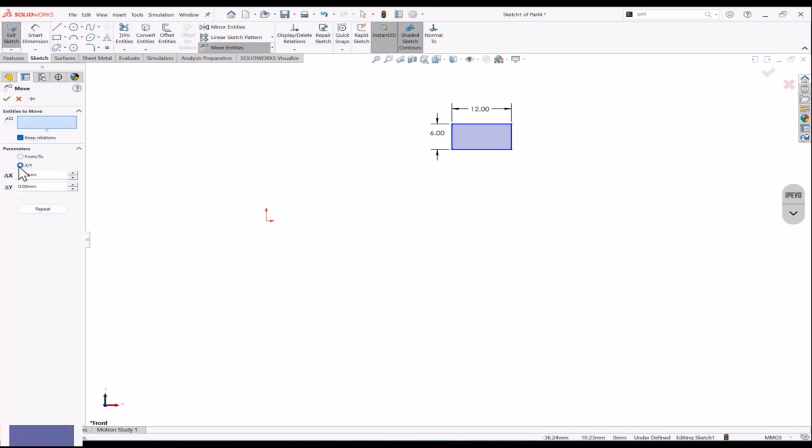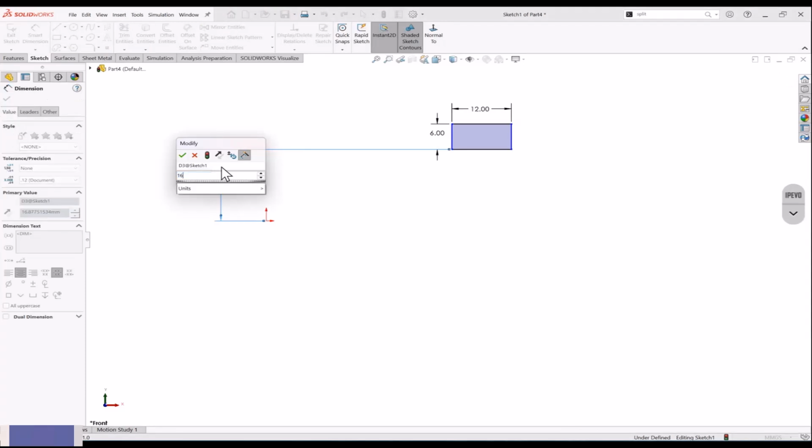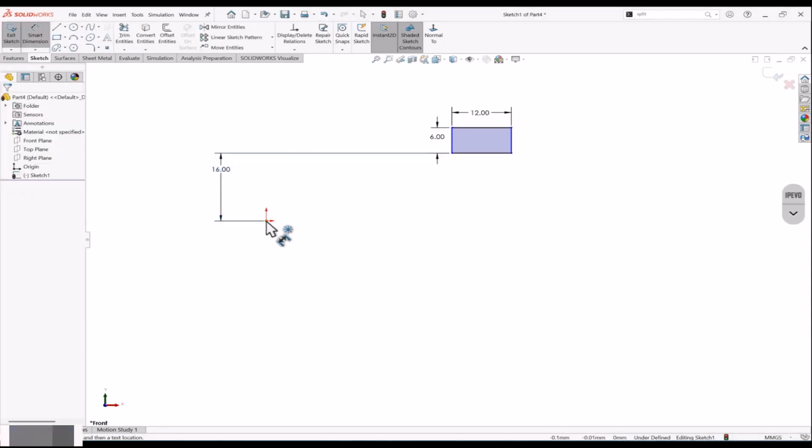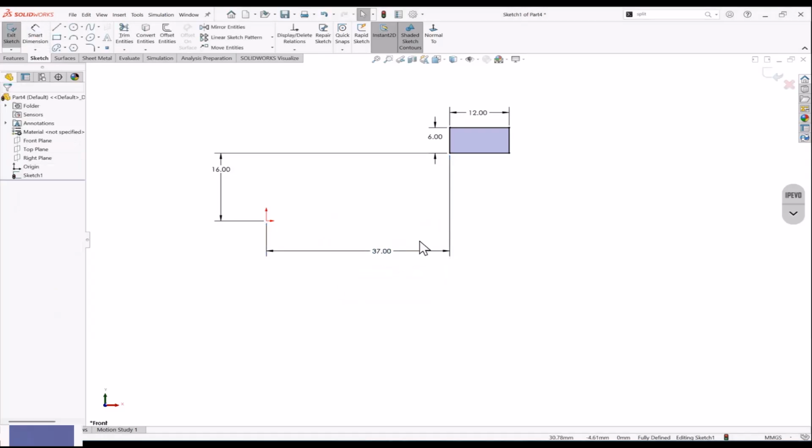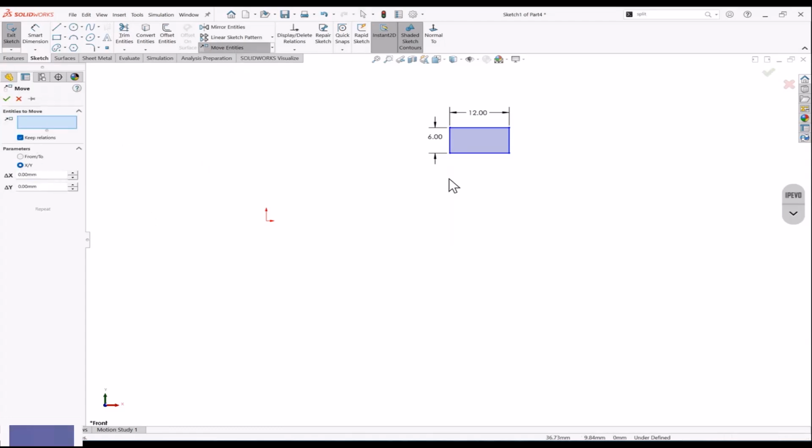Go to coordinates. Select this. For this, 0, 0 is this point. So if we know this distance, we can put negative values and we can place it there. Like if I want it exactly on the origin, let's calculate the point distance. So let's make it exactly 16. We should know. And let's make this also something, distance 37. Okay. I know 37 and 16 is my distance, right? Let's move it by coordinate. So I'll go here, I'll select this.